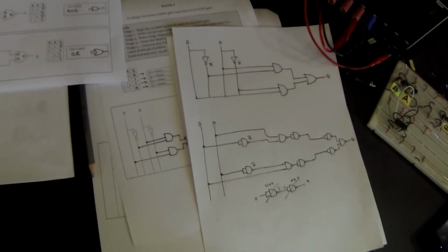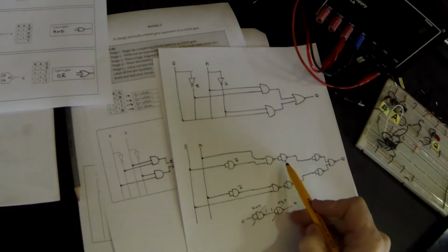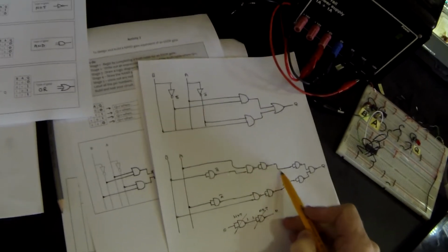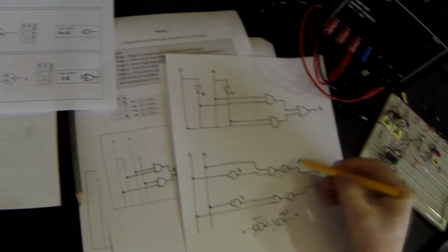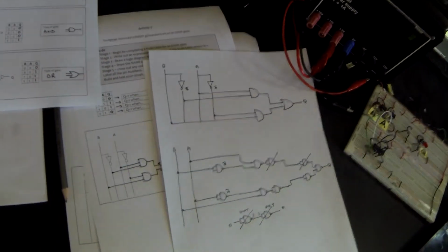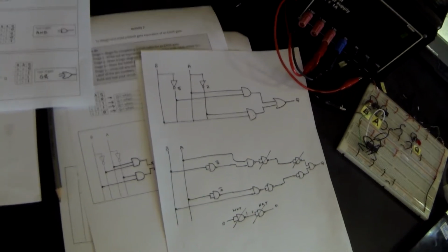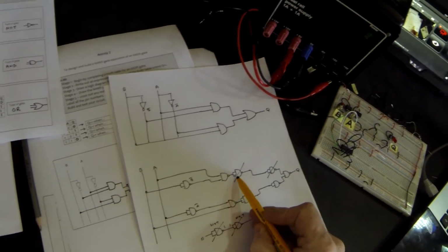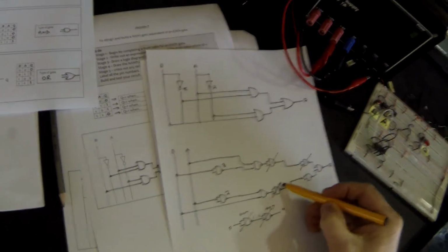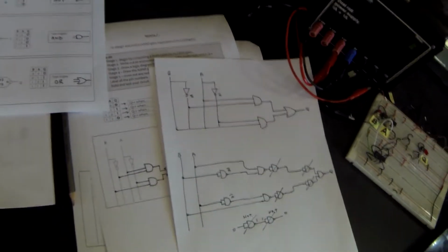So we can cross out all redundant gates in a circuit. And if we look here, well, I have a NOT gate, but it doesn't feed into another NOT gate. Here I have a NOT gate, and it feeds directly into this NOT gate. So therefore, I don't need that NOT gate, and I don't need that NOT gate. So I can cross them out. So where I've crossed them out, I'll be able to feed the output of that NAND gate straight into this NAND gate. If you look here, I have the same thing. Another redundant gate. So I've got rid of 4 gates.